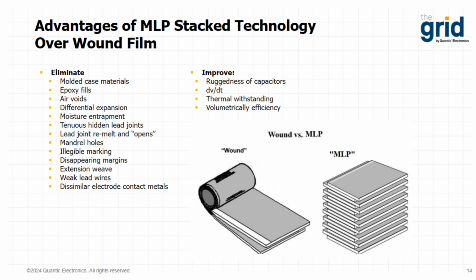So in order to create a very high reliability capacitor, we're sort of limited in voltage between the layers. We mitigate that by using a process called internal serialization, very similar to what MLC manufacturers will use for their higher voltage capacitors. But again, there are some considerations here.